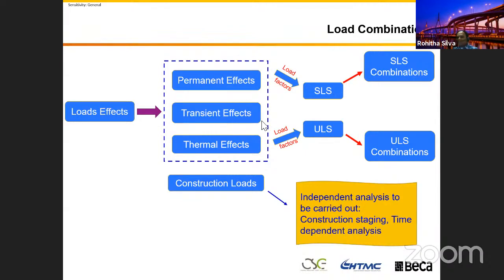Then we convert these effects into what we call serviceability limit state and ultimate limit state conditions using load factors, and then we combine these load effects appropriately to design the bridge.